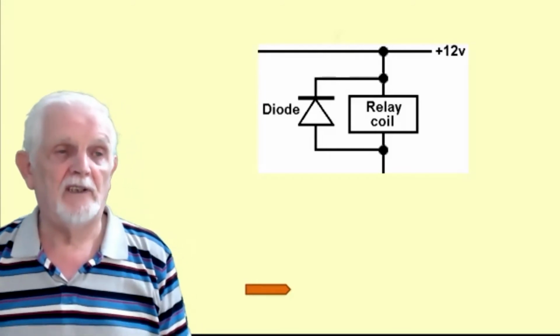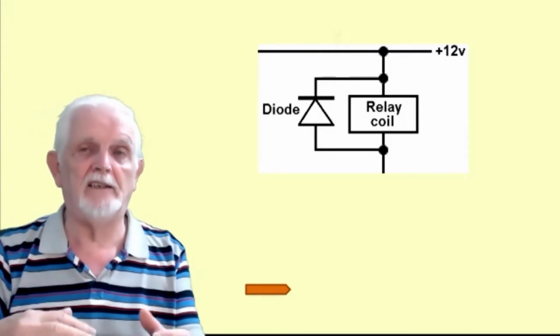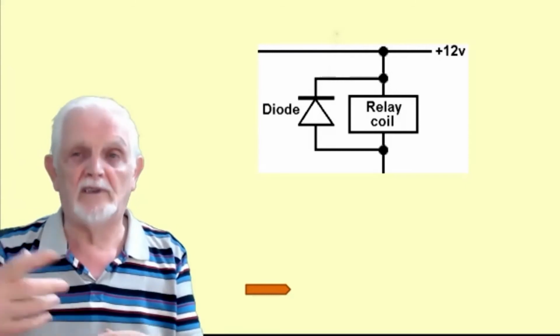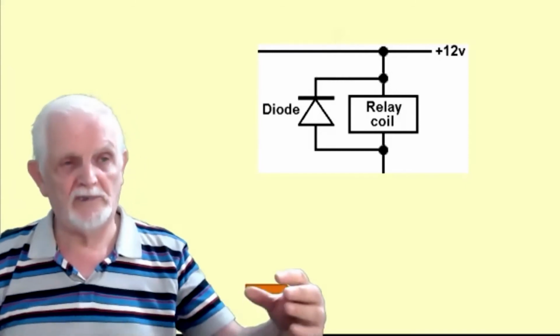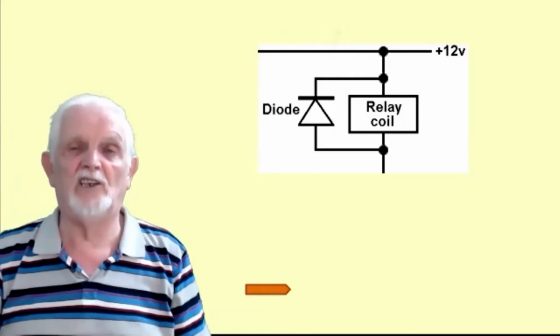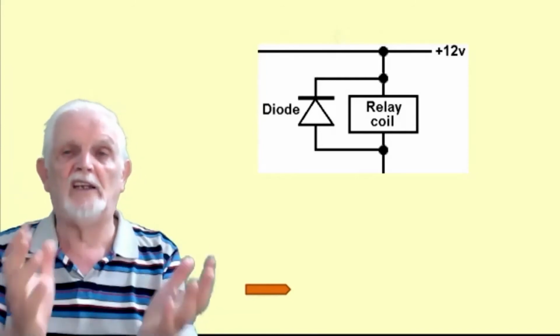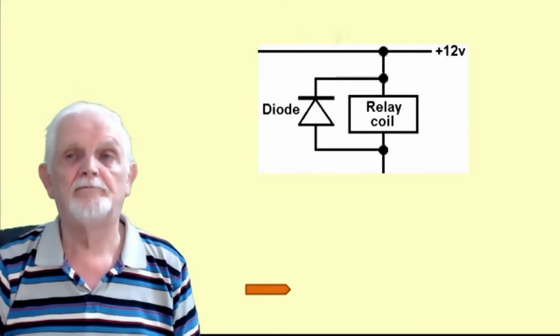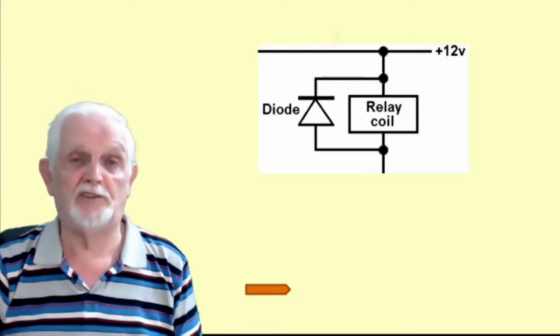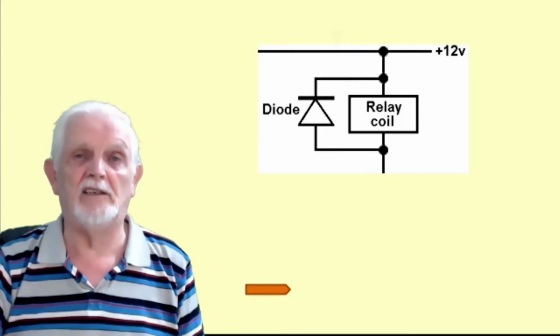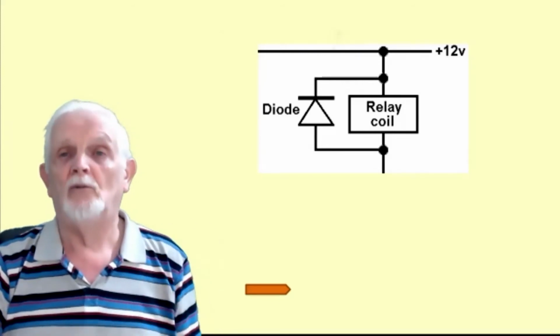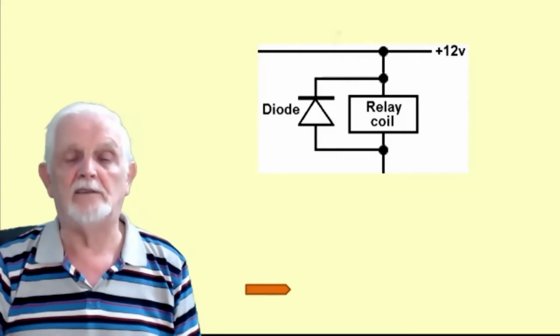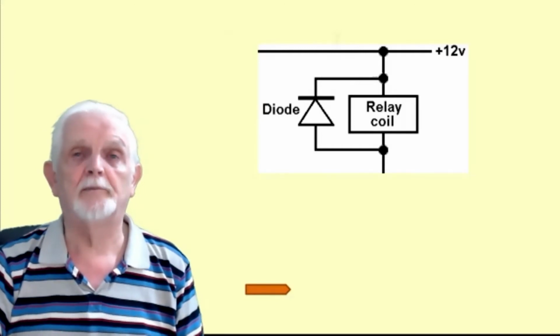So as long as the wagons are sitting in that siding, the conveyor belt constantly runs. When the train shunts out again, the conveyor belt stops. A little localized animation just by train detection. That's simply replacing the existing LED and its dropper with a relay and a diode, a bypass diode.